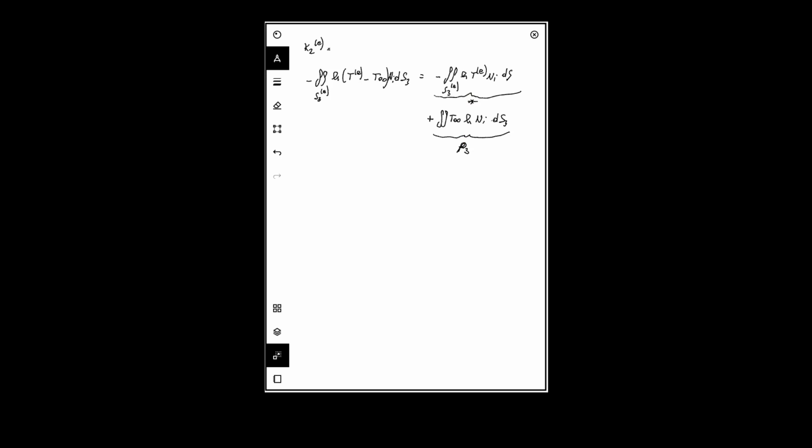So if we focalize on this term the attention, we will get the integral on S3 of h T E Ni dash 3, that is equal, considering what we have said before about the temperature distribution and the interpolation function, becomes h, the sum j equal to 1 to p of Nj Tj multiplied Ni dash 3.